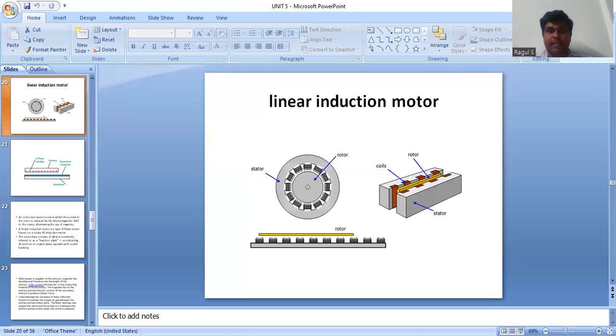The ferromagnetic plate, however, gets attracted towards the primary when the field is energized. Consequently, unequal air gap lengths result on the two sides of the plate. So a double primary system can be used to overcome this problem. That is why we prefer the double-sided primary.